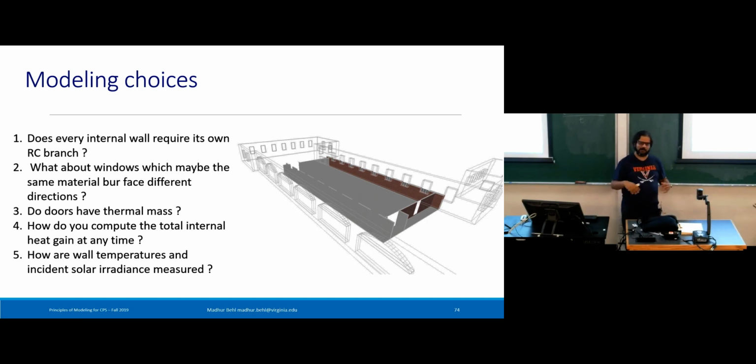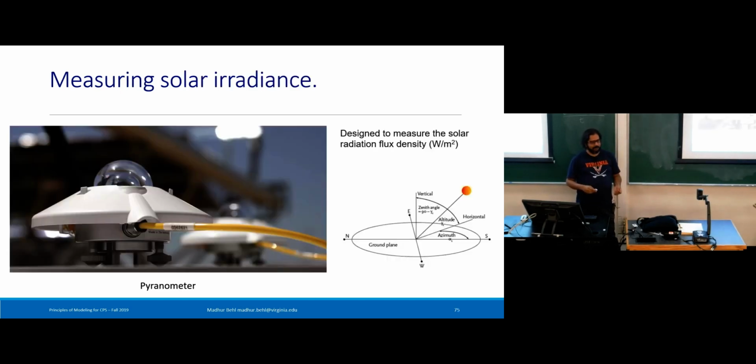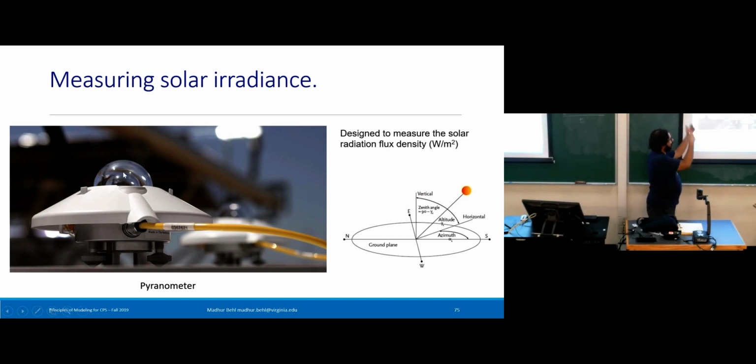You can measure the change in resistance by looking at voltage and interpret that as some function of flux or luminance. The same thing happens for irradiance, though it's a different part of the spectrum. The sensor is called a pyranometer. It looks like this UFO sort of sensor over there, but it has a dome to gather flux from all directions. Inside are special sensitive LDRs, which are sensitive to a range of infrared and ultraviolet, rather than just visible light.